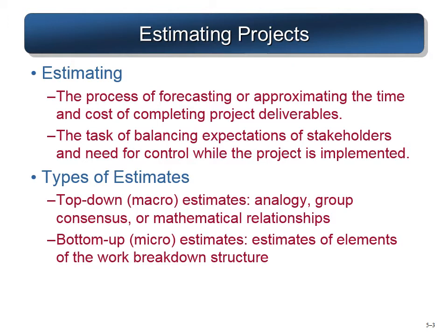The bottom-up approach is more detailed, where we try to estimate the cost of individual elements, add them up, and then arrive at the final cost of the project. When a project manager wants to get into a detailed estimate, he always tries to go for the micro estimate or the bottom-up approach, where it gives him more specific cost of individual items.